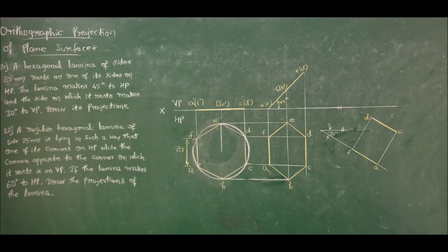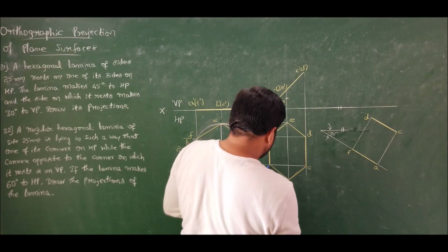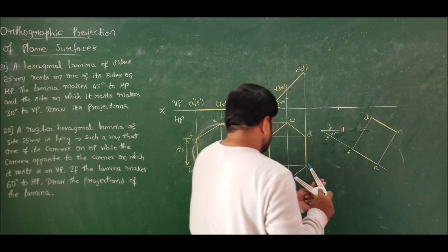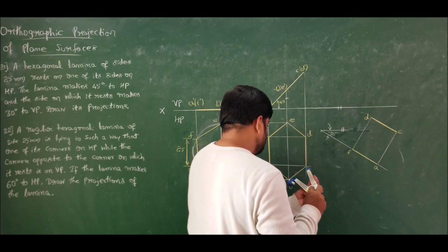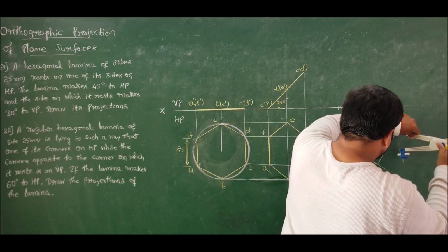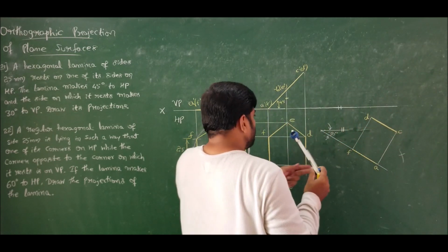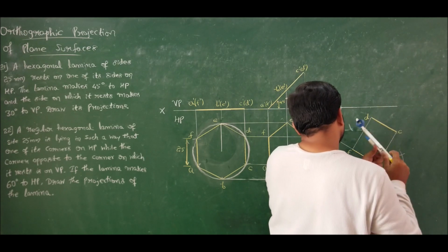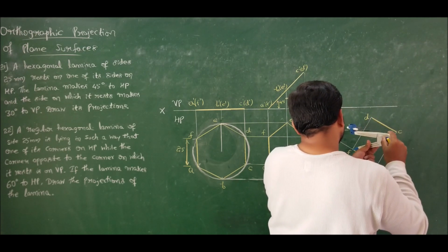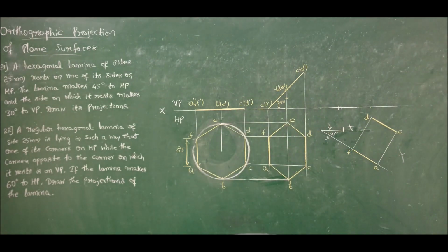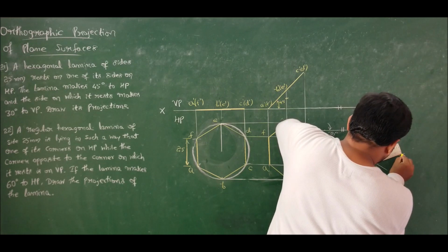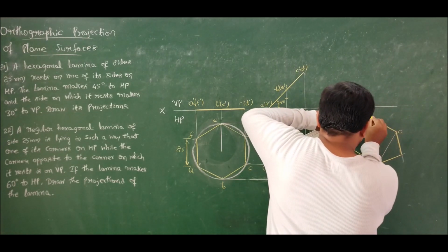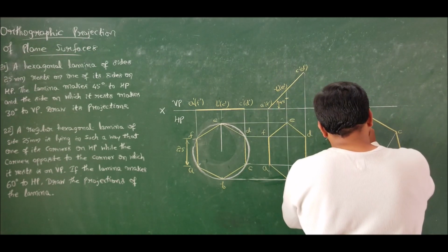Now using a compass I can locate corners B and E. So use the compass, cut an arc. Now measure CB and cut this previously drawn arc. So that will locate B for us. Repeat the same procedure to get E: draw an arc, cut this arc from F. Now we got all the corners, connect all the corners. This completes the final position, top view.